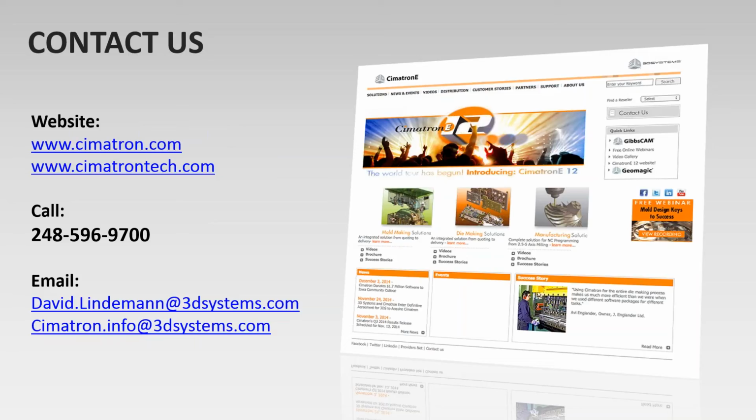Okay. Next question. When the printed core is hardened, what hardness is achieved? The answer I'll give you is based upon things I've researched myself, things I've found looking up this subject. So take it as a disclaimer: they're claiming, okay. What I found is that the achievable hardness is 50 Rockwell, using a 6-hour process at 900 degrees.